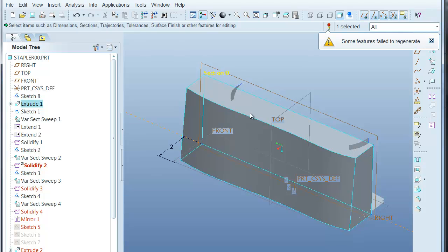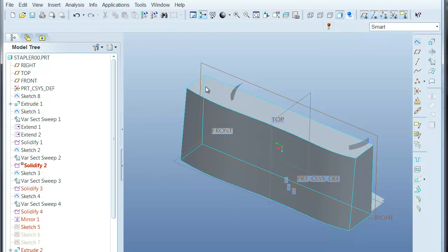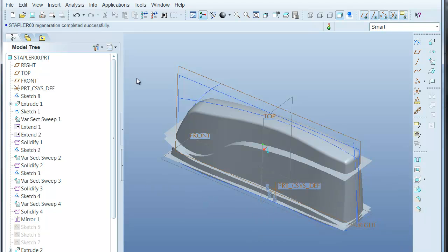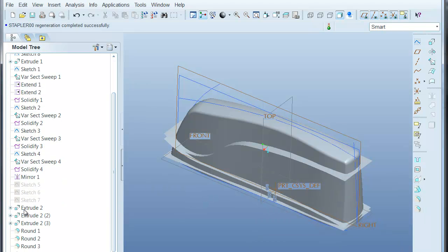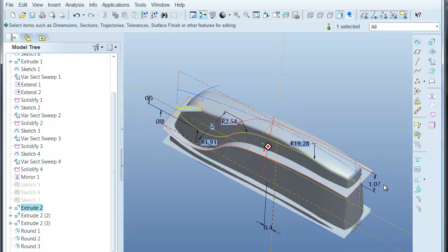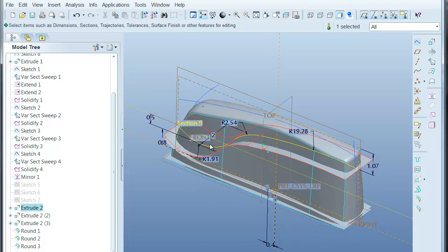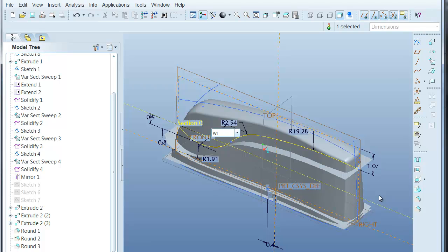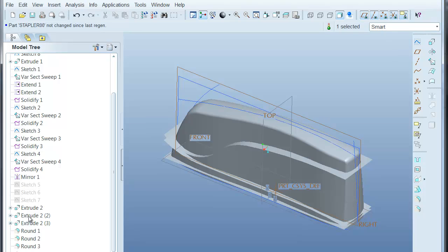Control G. Let's set this to width divided by 2. Okay, and there's probably a handful of others. Each one of these needs to have a width dimension. This one's the entire distance, so I'm just going to call that width. Do that 3 times.